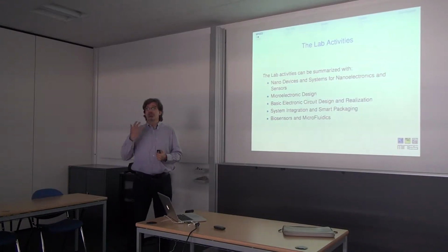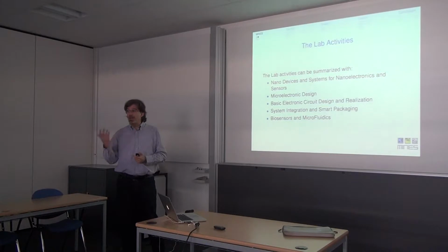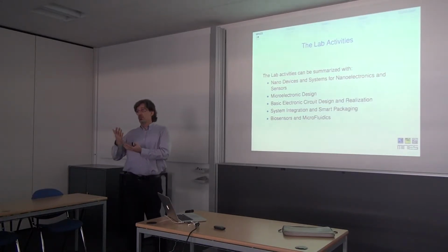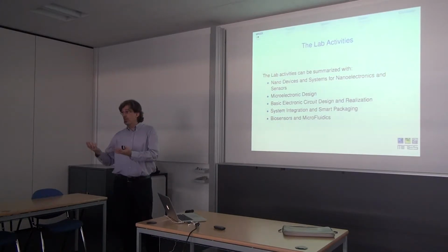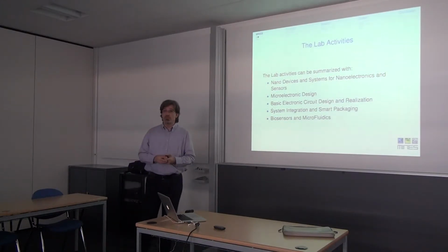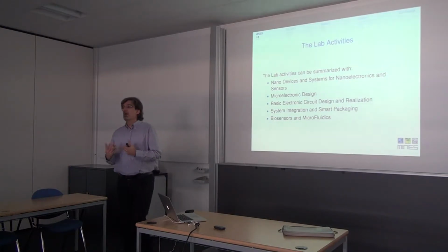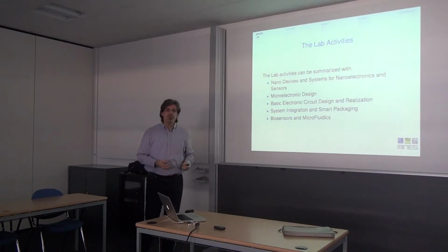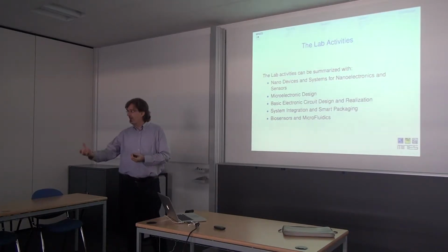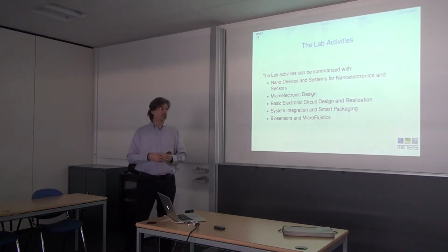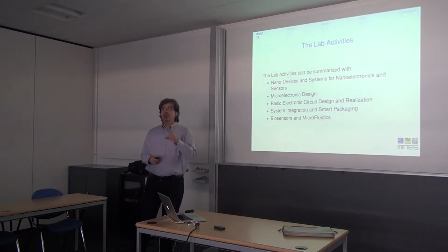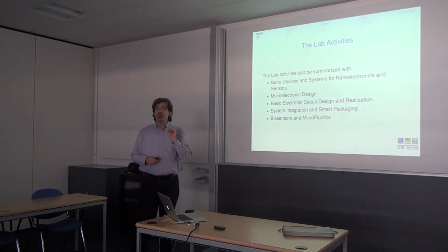So we do the system integration and also the packaging, because I'm sure that you know very well that packaging, talking MEMS and now NEMS, is one of the most important parts. Also talking about money, about the cost of the final product, because quite often the package is more expensive than the device itself. And so you must put a lot of effort into finding the most efficient, the least expensive package